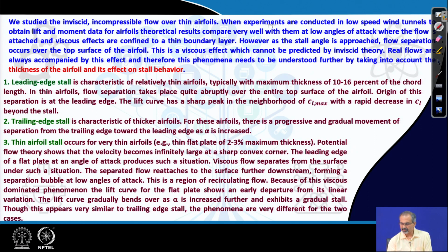When experiments are conducted in low speed wind tunnels, and lift and moment data for airfoils are obtained, they compare very well with the theoretical results, that means the potential theory results. They do compare very well at low angles of attack, where the flow is basically attached and the viscous effects are confined to a thin boundary layer. But as stall angle is approached, we see flow separation takes over, and the flow separation phenomenon is much beyond the inviscid theory, and therefore, inviscid theory cannot predict it.